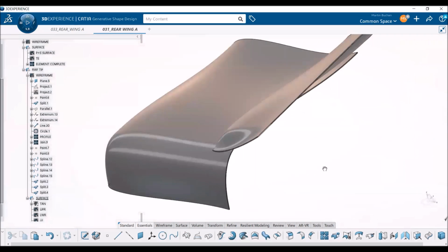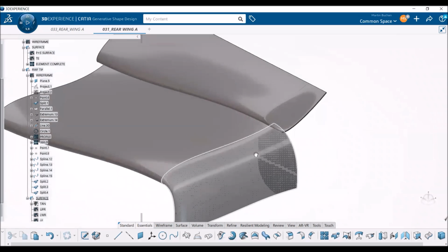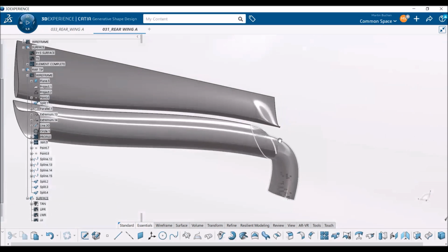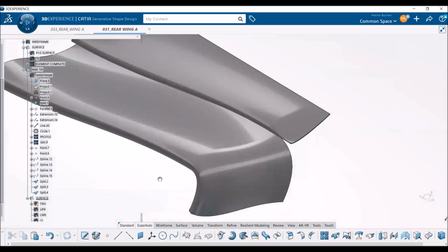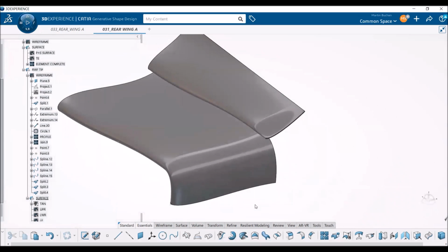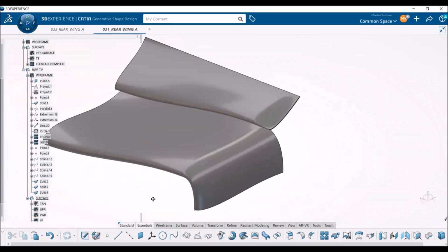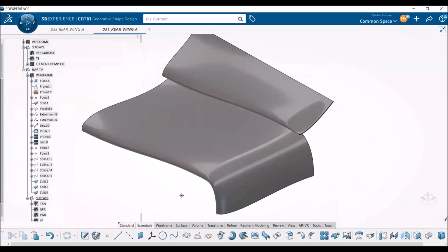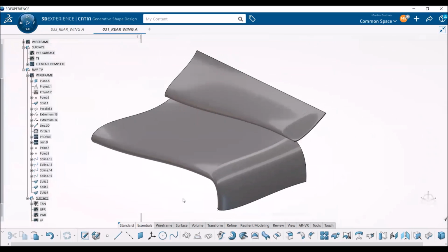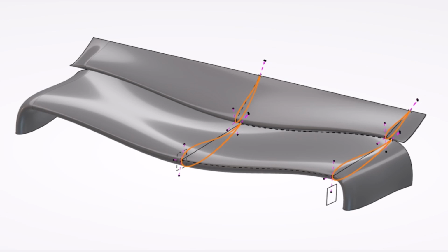It's only that the upper bit is changing a bit because there's so much side flow that you want a trailing edge on the side of this element. And this is why we use these kind of features. It just creates a bit less drag, it's a bit more elegant. And you could now also go on and change the leading edge to be a bit rounder at the side, just like what we saw at Alpine and Alpha Tauri. But this is the general process of how you design such a tip feature.